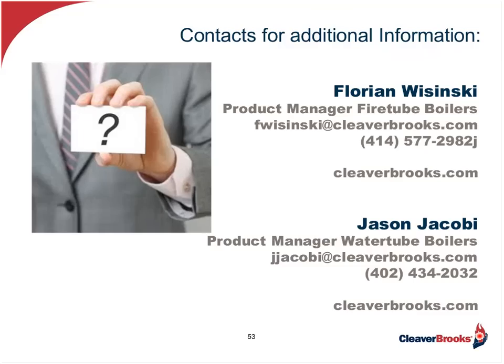Again, that's a very generic question. In the building heating side, there've been tremendous advances in boilers in the last several years from an efficiency standpoint. What's key here is getting someone to assess the basic building. You have to determine if you're currently on high pressure steam, low pressure steam, or hot water, and you have to look at the size of the coils and the type of system that you have. But there is the opportunity, either with a condensing boiler or some of the hybrid systems that we have available that mix some of the older systems and the new condensing, for significant fuel savings on the heating side. But you would have to go out and take a look at the boiler room and at the building itself to determine what options exist. But the potential for significant fuel savings exists.